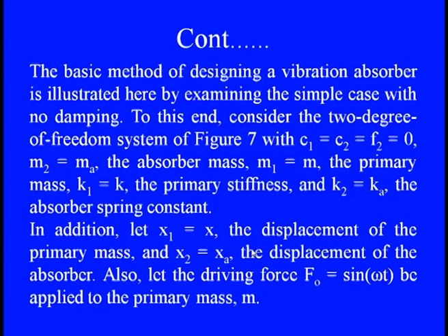In designing, when we are choosing those values, we need to see what kind of displacements come out when we are not disturbing mass m1 and only mass m2 is disturbed, or when we put the force on the primary mass m1 and not on the secondary mass, and then accordingly we can choose the absorber at mass m1, m2, or the source from where these displacements are being created.